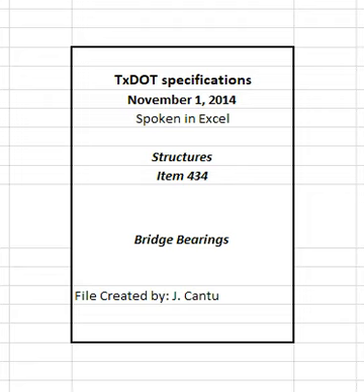3.2.3 Storage. Store sliding elastomeric bearings horizontally in a dry, sheltered area. Provide moisture and dust resistant wrapping maintained in good condition until installation. Lift bearings only from the undersides. Protect bearings from damage, dirt, oil, grease, and other foreign substances.